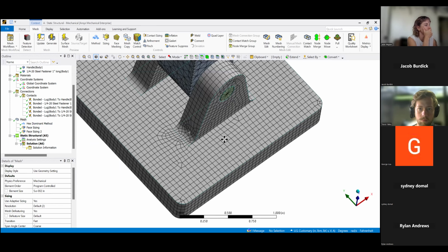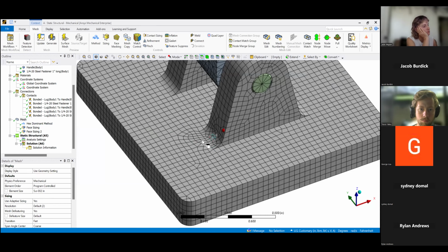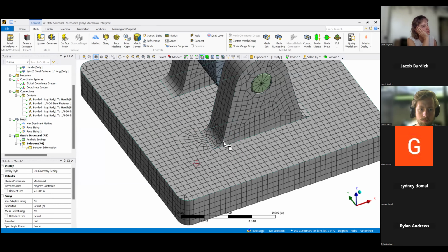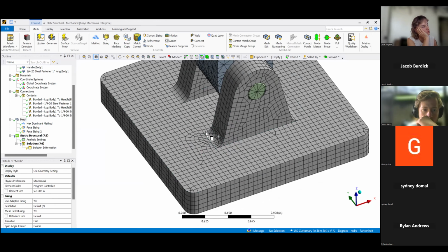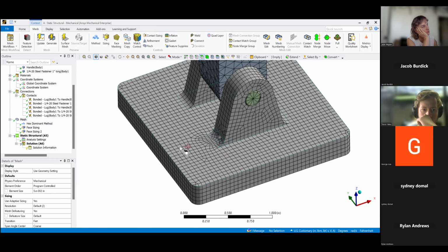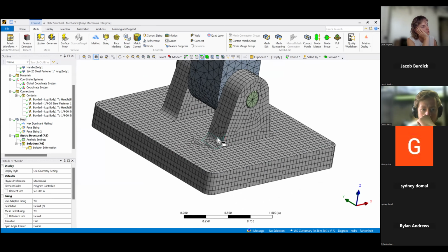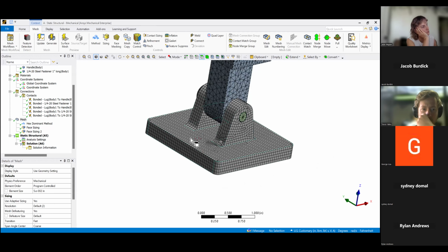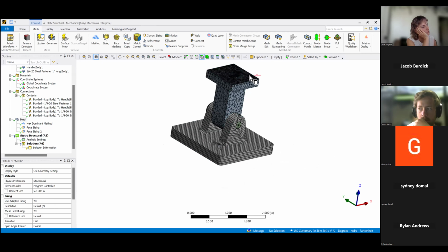Yeah. So as you can see here, you kind of have that circular effect. Probably not the best idea to use with hexahedral meshes, purely because that's a square and you're messing with a circular pattern. So probably save a sphere of influence only to be used with a tetrahedral one. So there's that. Those are, I think, most of the mesh manipulation tools that you could use throughout your study that are useful, I would say. So pretty much making your mesh smaller, making it coarser in certain areas, changing the mesh type or the element type to fit your specific requirements.